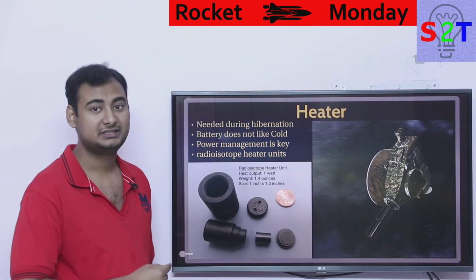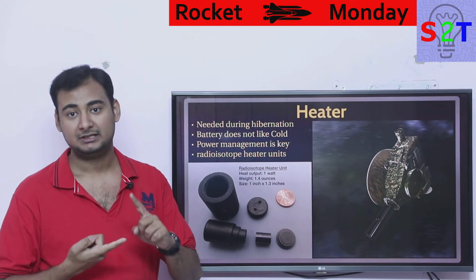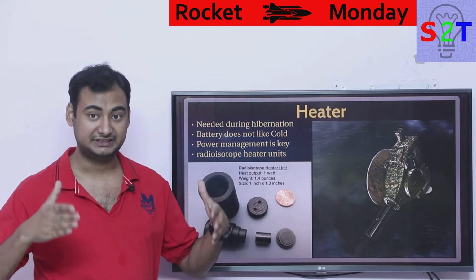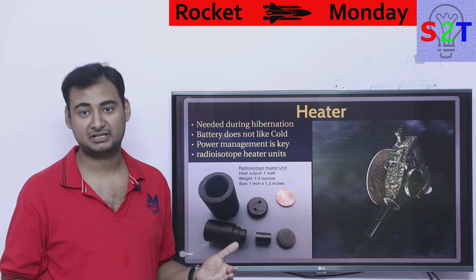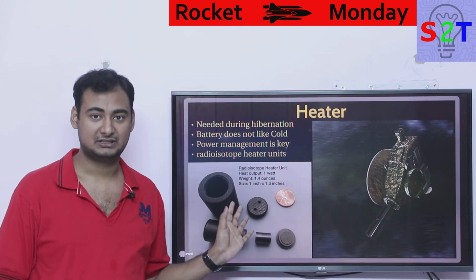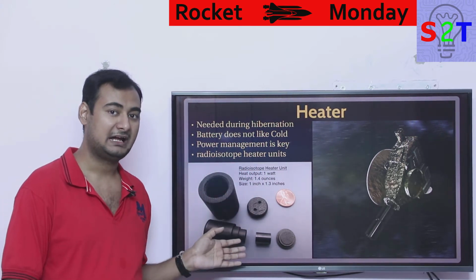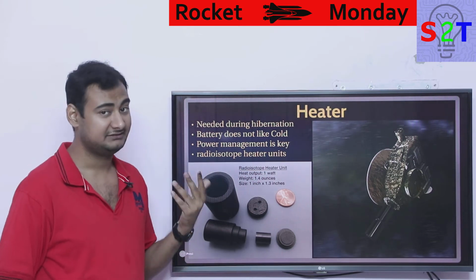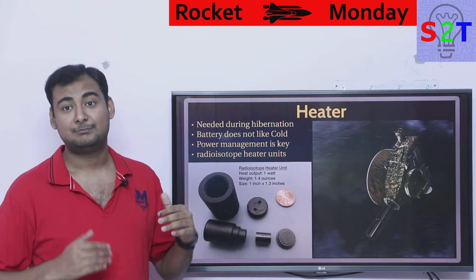The reason why it's so little is that it should be there to, A, keep the battery from freezing, and B, overcompensate for the heat loss of the insulator, because no insulator is perfect. Blackbody radiation will still happen, but if, let's say, the insulation is losing half a watt, you will add 1 watt to make sure it never goes below a certain threshold. Now the battery flat out does not lock out, and on top of that, power management is an issue.